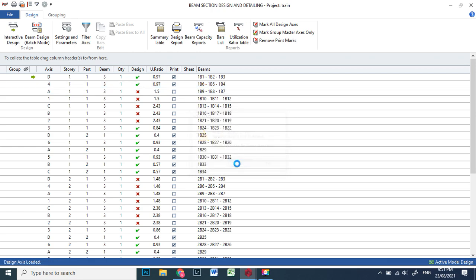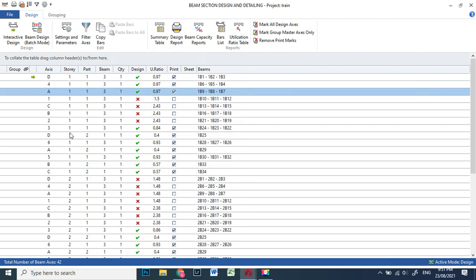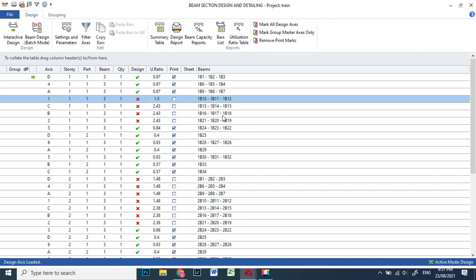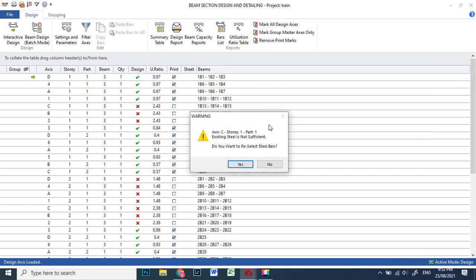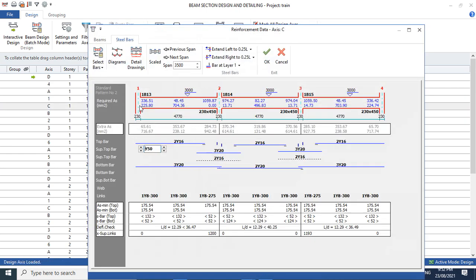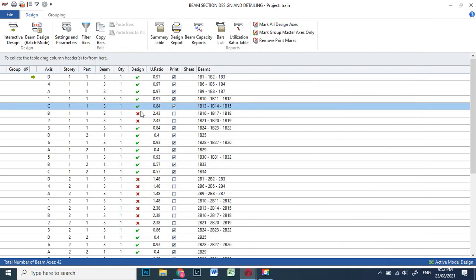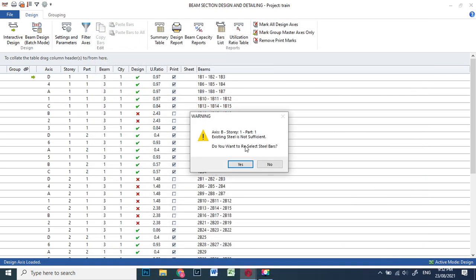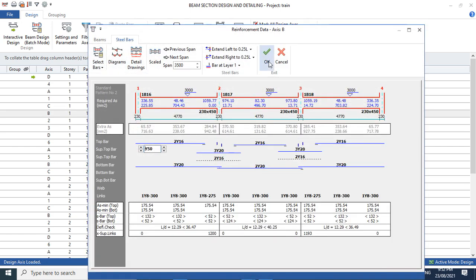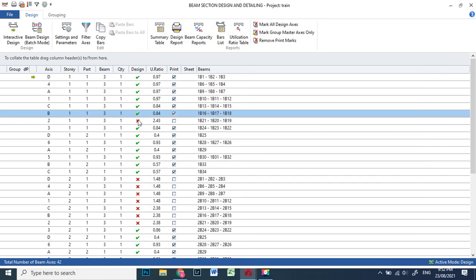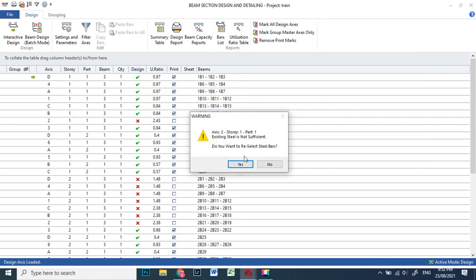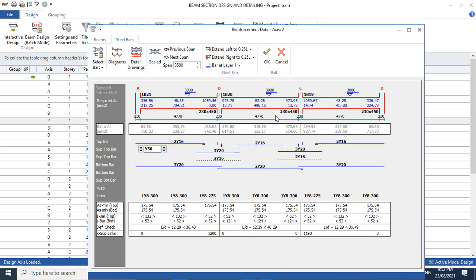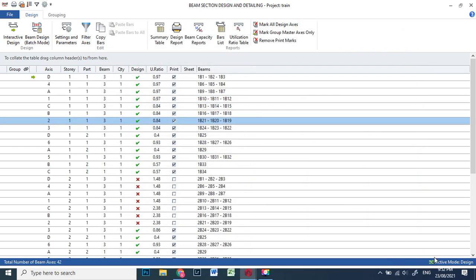Please pay attention to that. If there's any you've not designed and you move straight to Prota Detail, some of your reinforcements will be omitted in the drawing. You just see an empty formwork with no reinforcement inside. Very, very important that you do this.